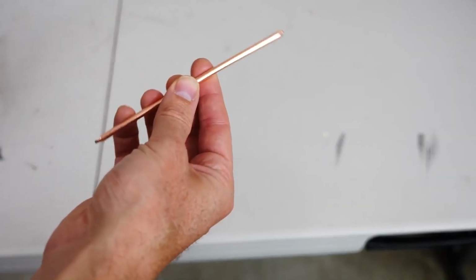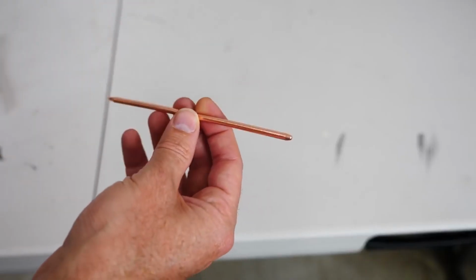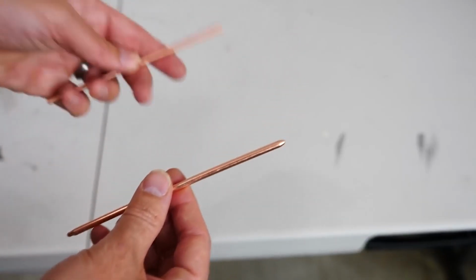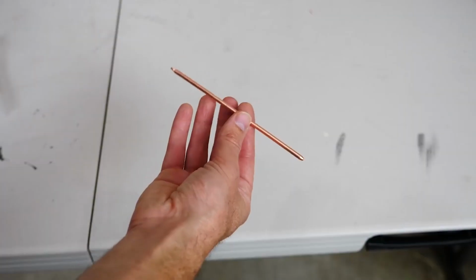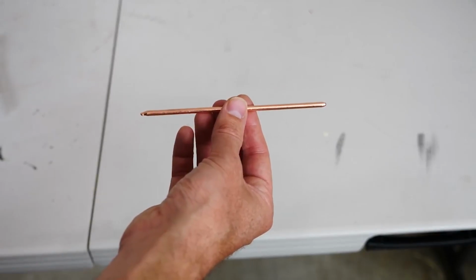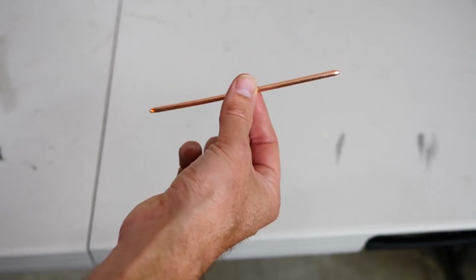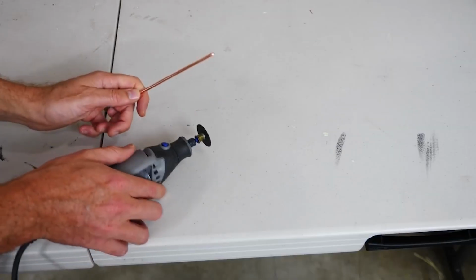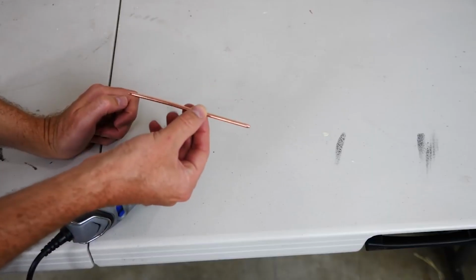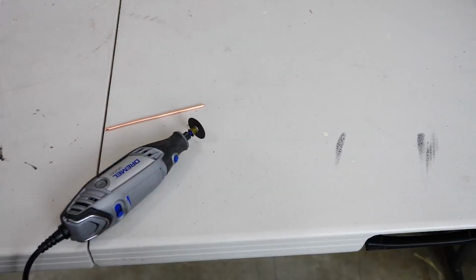So let's cut this open and see why this can transfer heat so much faster than a regular copper rod. This can actually transfer heat around 2 orders of magnitude faster than a copper rod. So copper can transfer heat at around 0.4 kilowatts per meter Kelvin, and this heat pipe can transfer at 100 kilowatts per meter Kelvin. So what's a little bit scary about this is, as I'm cutting it, it's going to generate heat, but it conducts heat so fast that it'll probably burn me. So I'm going to wear some gloves while I hold this.